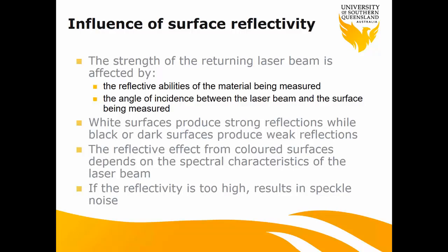That's why in the laser scanner, or even in airborne LiDAR, you directly get three-dimensional point data, but at the same time you can also get intensity data that reflects the returning signal's strength, or how strong your reflected laser beam is. That's mainly related to the surface material.